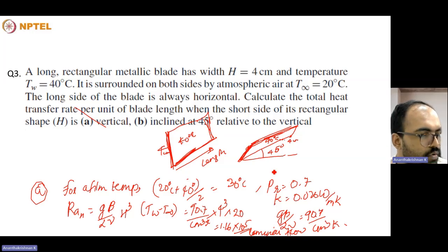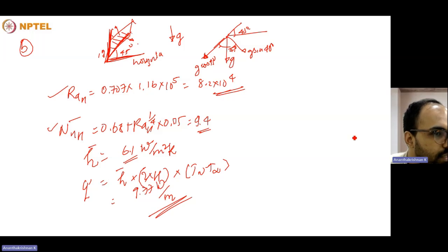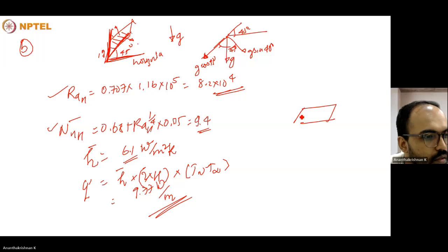So the hot air will remain close to the lower side of the plate, while the lower temperature cold air will be farther below. What I meant to say is that if you tilt the plate completely horizontally, on the top side there will be significant heat transfer because the surface is at a higher temperature compared to the ambient, so there will be natural convection.